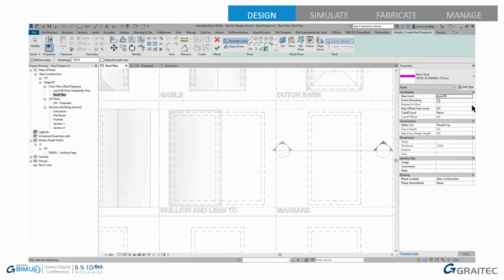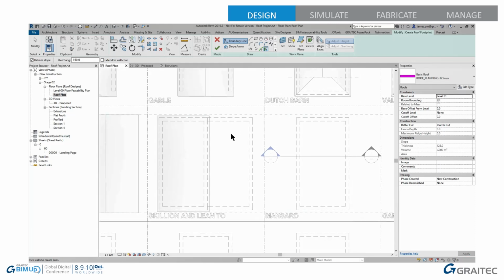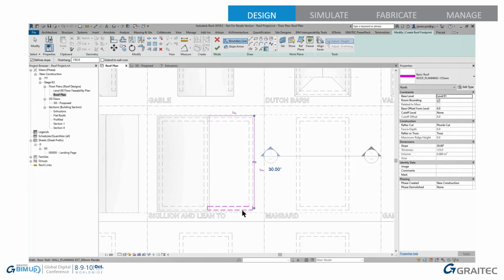So this time I'm going to do a roof at a different height. I'm going to associate this to my first floor, not the roof level. And again, I'm just going to do the same technique as I did before, but this time the intersecting wall, I'm going to go pick line across the face of that. I could lock that on there as well if I'm being good with it, so in case that wall moves, the geometry will move with it.